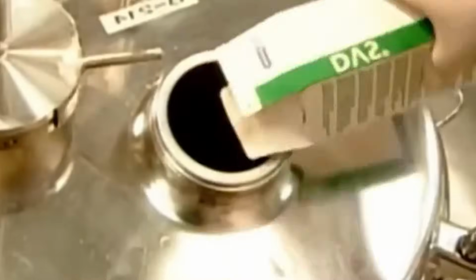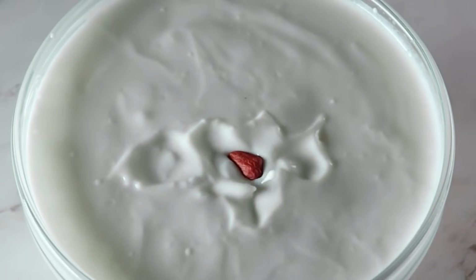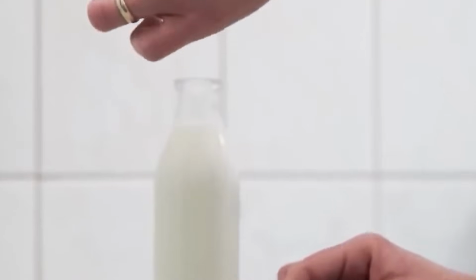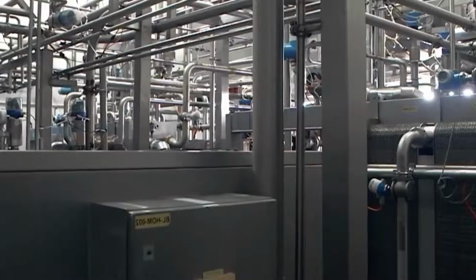Sweeteners such as sucrose, glucose syrup, fructose, or high fructose corn syrup are stored in either crystalline form or heated tanks depending on their physical state. Crystalline sugars are conveyed to mixing tanks via screw feeders or pneumatic conveyors, while liquid syrups are pumped through heated, jacketed pipes to maintain constant viscosity. The addition rates of each sweetener are determined by pre-programmed recipes in the batching software and are adjusted in real time based on inline refractometers measuring total soluble solids.